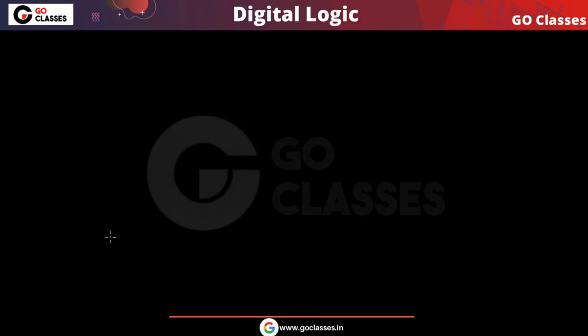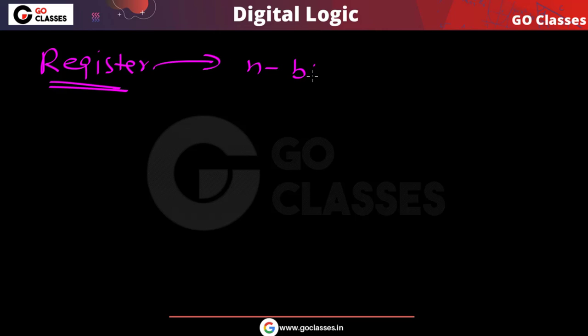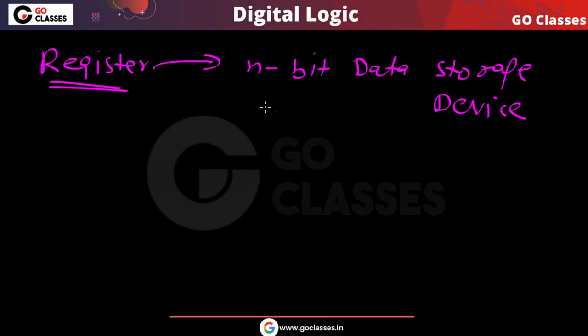Each and every type of register we have already seen. First we have seen the definition of register, then we have seen the types of register. What is the definition of register? We have seen register is nothing but an n bit data storage device. Register is basically using n flip-flops, because one flip-flop will store one bit. So using n flip-flops you can create an n bit register. It means this n bit register can hold n bits of information. So this is an n bit storage device.